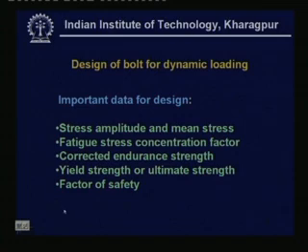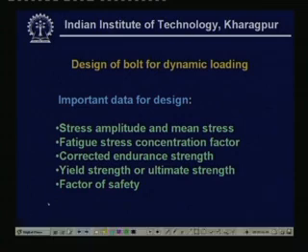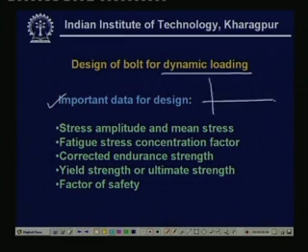Now, design of bolts for dynamic loading. Here the dynamic loading is very important, and when we design the bolts for the dynamic loading, then some important data are to be considered. The first one is the stress amplitude and mean stress. That is very important, and you have already learnt about it in the design of strength.